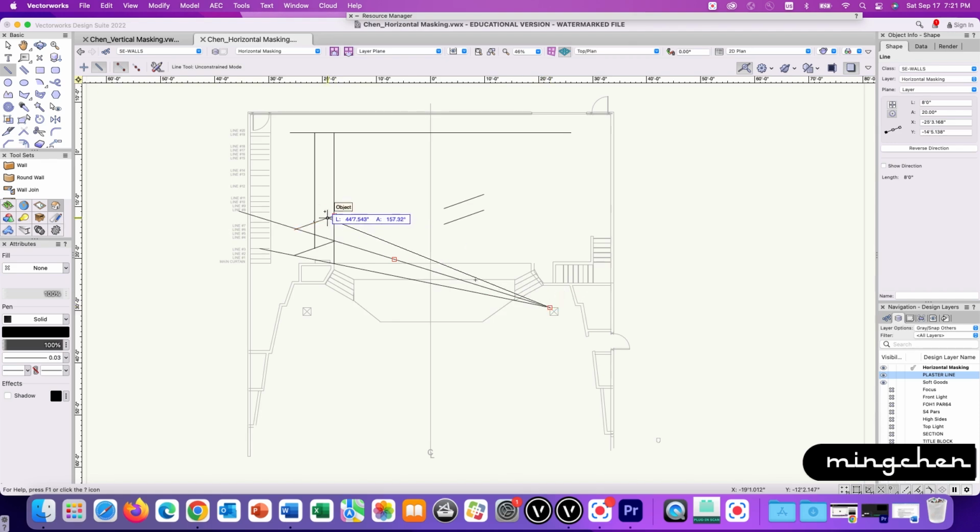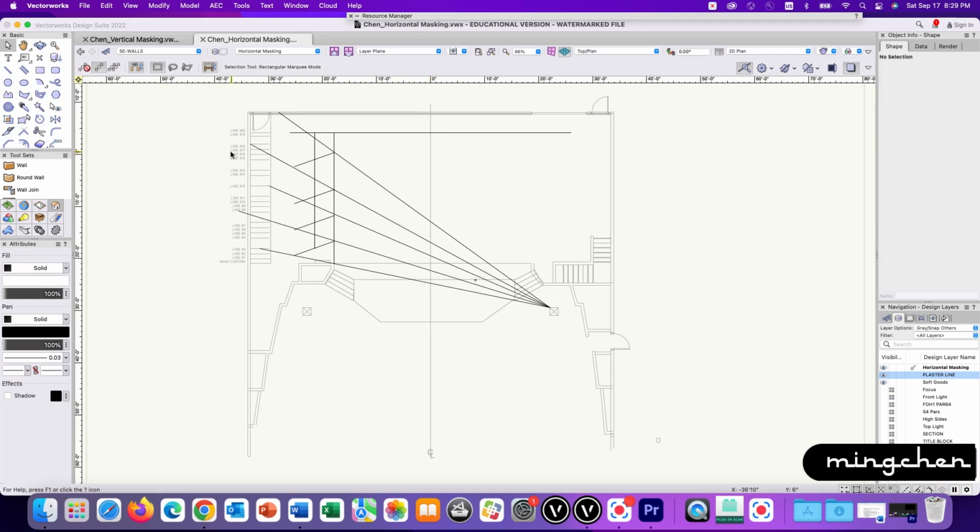Continue to check the sideline and place the rest of the 2 legs in places so that they will block all the offstage space on stage right. After you have installed all the 4 legs, select all the legs. Click on Mirror tool located on Basic Palette.